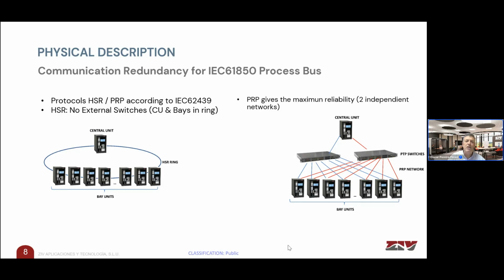Why? Because you are not introducing a new vendor or a new device in the system. So in case of a problem, if you are following an HSR, the problem is focused on the same vendor and on the same kind of equipment. However, if you have an arrangement involving switches and any problem happens, the solution could probably be more difficult to identify. So please keep in mind that only these two are possible, HSR or PRP, with HSR being the most frequently used.